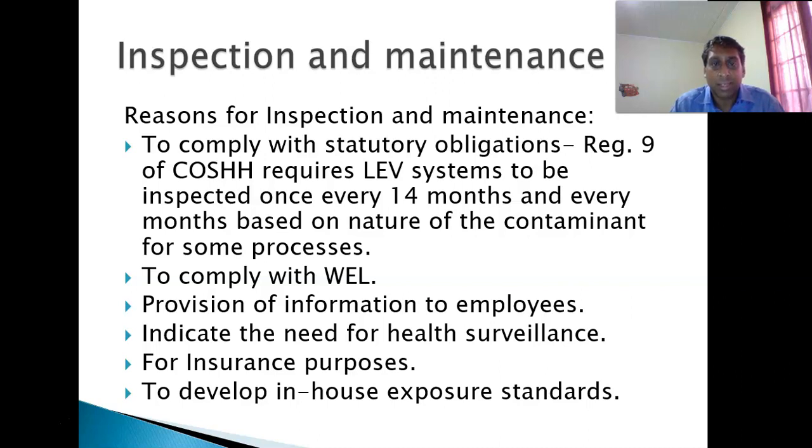Simply saying, if you have a lot of dust there, or a lot of contaminant, you may want to inspect every month based on the quantity of contaminants being suctioned through the LEV system. Reasons for inspection and maintenance: to comply with the law, to comply with a workplace exposure limit, provision of information to employees, to indicate the need for health surveillance, for insurance purposes, and to develop an in-house exposure standard, which of course would have to be less than the workplace exposure limit.